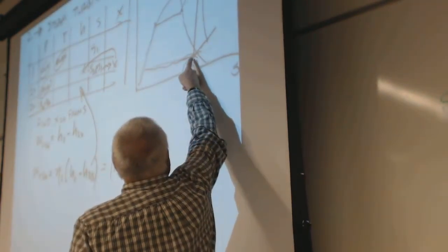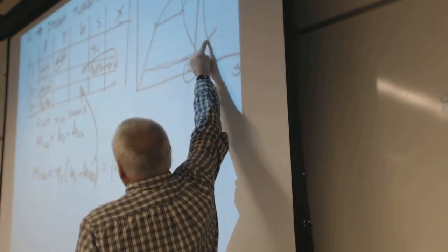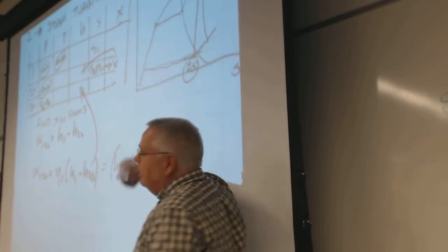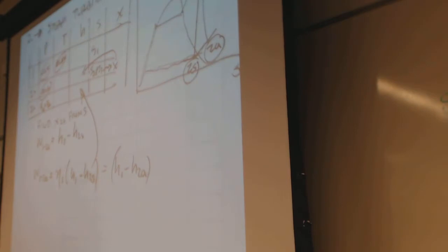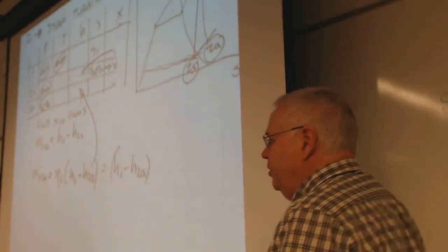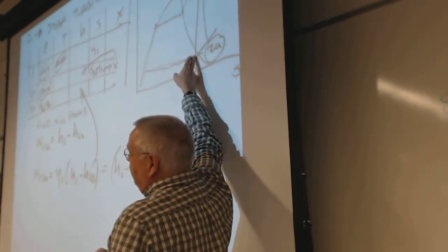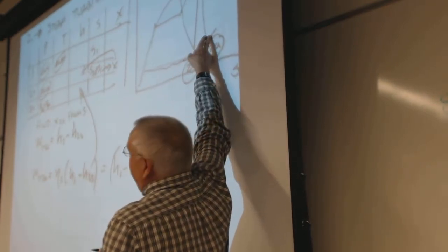If this came out of the saturation curve, the temperature would rise. It's the same pressure, and if it was out of its saturation value, then it would be out here somewhere, and your 2A would be up a little bit. That's actually probably how you'd use it to measure output. Set it so it comes out with a really high value here, and then you can measure the temperature pretty easily.